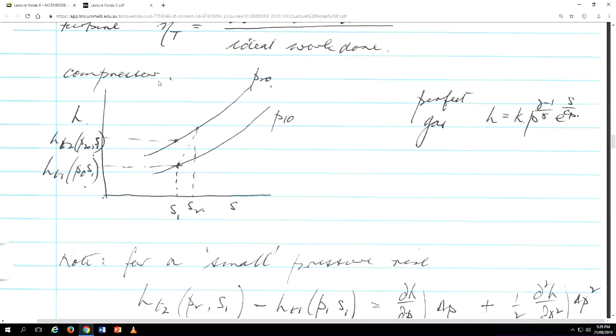So I bring the fluid to rest, and I measure the total temperature. And that's not so easy to do. In principle, you can do it with a thermometer, and you bring the fluid to rest. But as I've said to you, one of the subtleties is that when you try to measure the total temperature, if you've actually got large gradients, large stresses or large heat fluxes, then it won't be the right total temperature. But anyway, let's suppose that's what we did.